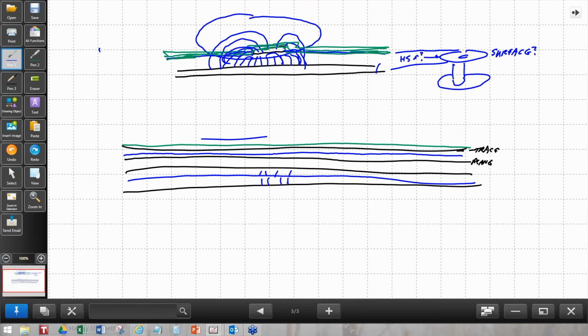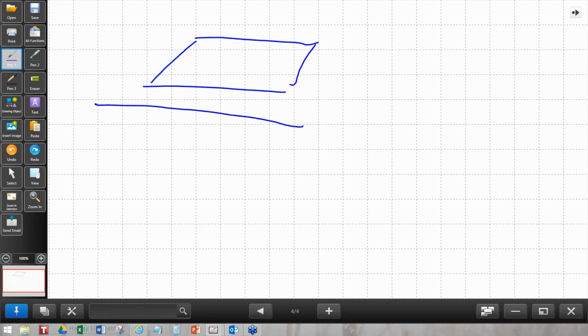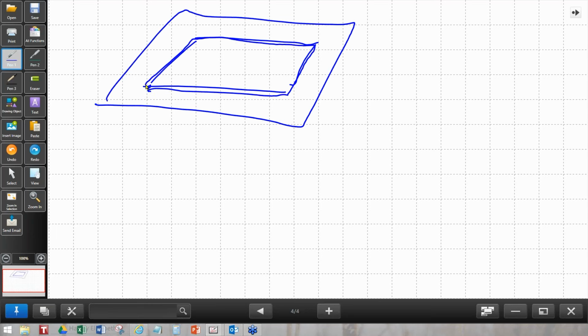There are a few rare things that are done with solder mask that I've seen. Sometimes people will say, I want to put solder mask on the outside because this board has to be sealed in some kind of a place, and I need to make sure that no light can come through this board because there's light on one side and not on the other, especially if it's some kind of photographic or imaging type board, in which case they might use black solder mask just to basically block light from making it through the board and also through the holes and vias.